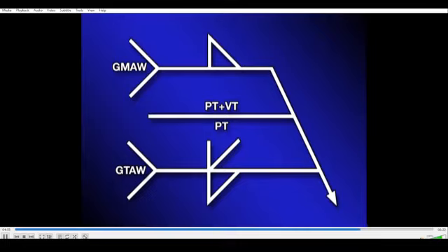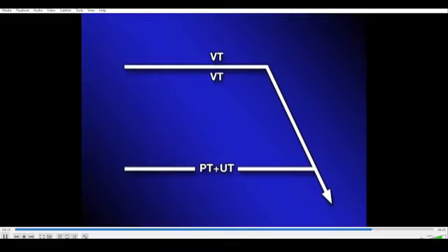The order in which the operations or tests are performed is indicated by the order of the lines, the first operation being closest to the arrow and the last furthest from the arrow. For example, these multiple reference lines called for liquid penetrant and ultrasonic inspection to be applied with no particular side significance. The second operation specifies visual inspection to be performed on both sides.